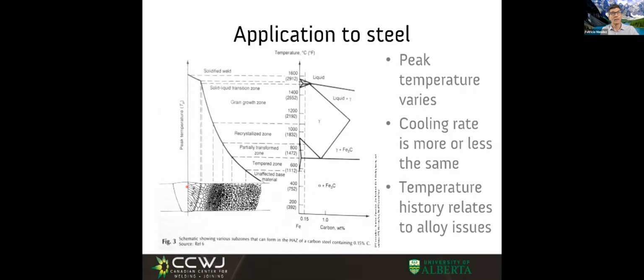And solid state welds also have a heat affected zone. But I don't want to discuss those type of processes now. I want to do the easy ones. So I know near the center line of my weld, inside the weld pool, I reach melting temperature. And in the center line, it's even higher than melting temperature. Some cases can approach boiling temperature.